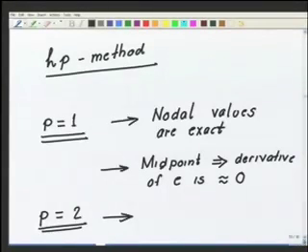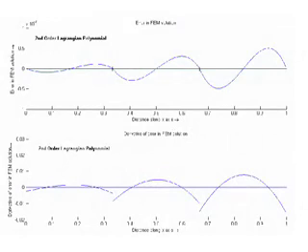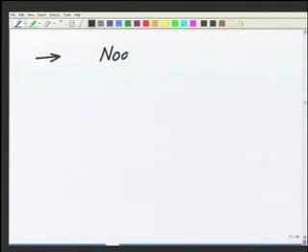Okay, so if I look at t equal to 2, then we observe that the nodal values are exact, and at some point in the middle, most probably at the center of the element, which is also for the Lagrangian element a node, a solution node. At these 3 points we find that the solution is very good. Okay, but really speaking, we can only say in the general case, though for this one we observe these things, that the nodal values are exact.